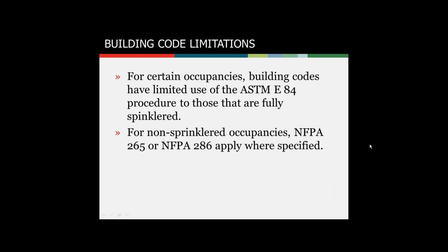And these tests can be quite more severe than the ASTM E84. However, that is not really the topic of our discussion today. I just thought I would point this out so you would have a bit of general background information if anyone ever mentions the NFPA 265 or the 286. But generally in a sprinkler building, the ASTM E84 is the code of choice.